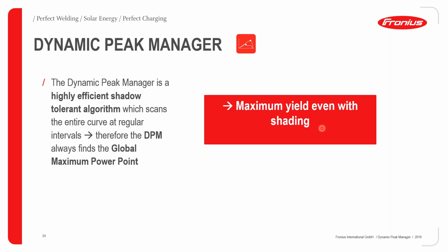Something else I can mention about the FRONIUS string inverters is that together with global maximum power point tracking, the inverter itself has another feature that electronically boosts the voltage coming from the string arrays. This ensures that the MPPT operating point inside the inverter is as close to the optimal operating point as possible.